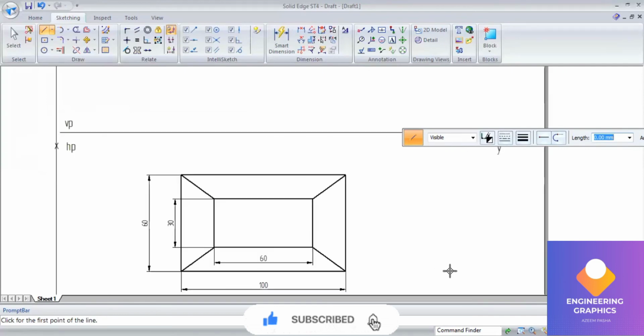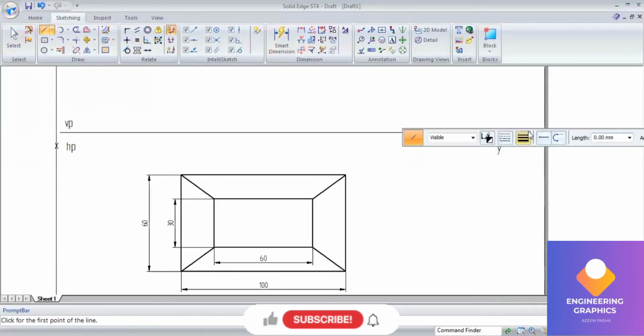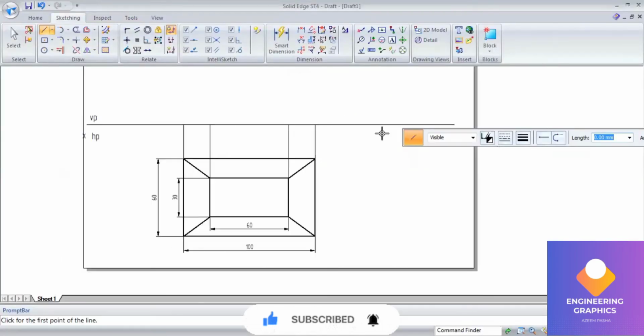Okay, so the top view is over. Now we have to draw the front view. For that we have to draw the projection lines. So first we construct the projection lines here. So draw the front view just by extending the lines here. For a height of 40, I'm going to join it.